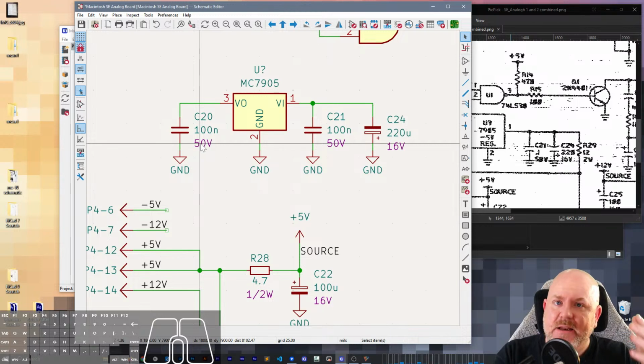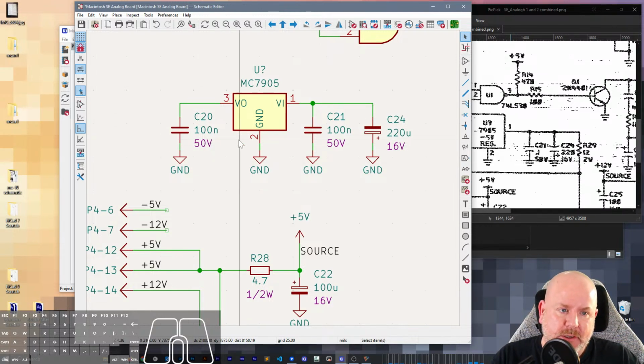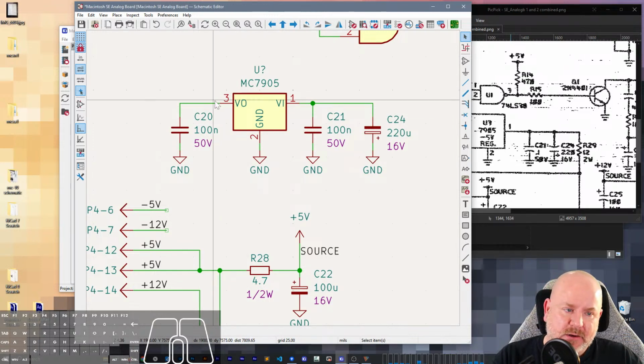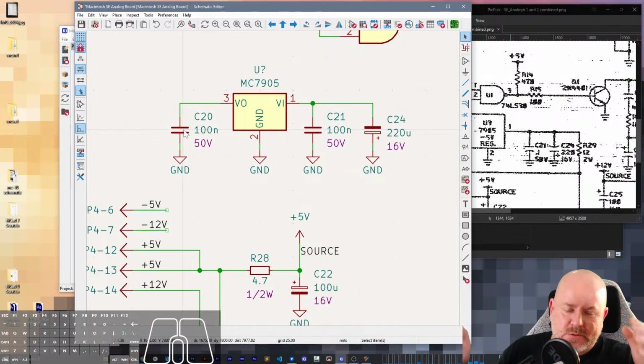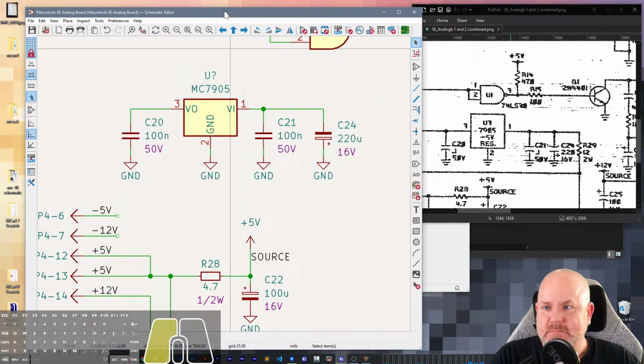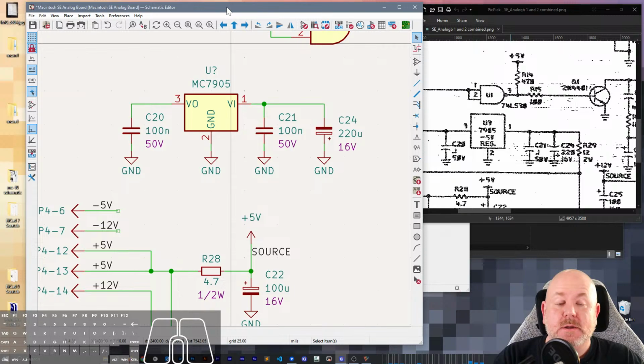Now, if your load needs a decoupling capacitor, you want that big cap physically separated from the output pin of the regulator, because the regulator is trying to monitor the change in output voltage as best as it can. If you've got a big cap out there holding up the rail while it's sagging somewhere else, then you're going to get ripple. So the more you know.